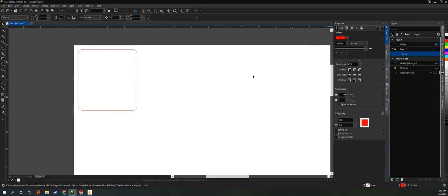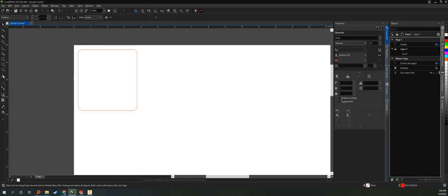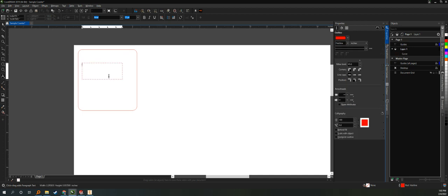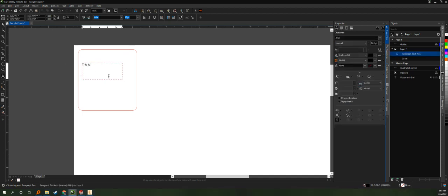If I wanted to engrave this entire coaster, any image with any thickness, even if it was letters, text for example, would be a black. Anything with a thickness is going to be an engraving into the material and set by black. So if that was the case, I would write text, go over here, click the text option, drag drop. All right, this is fun to learn Corel. Perfect.